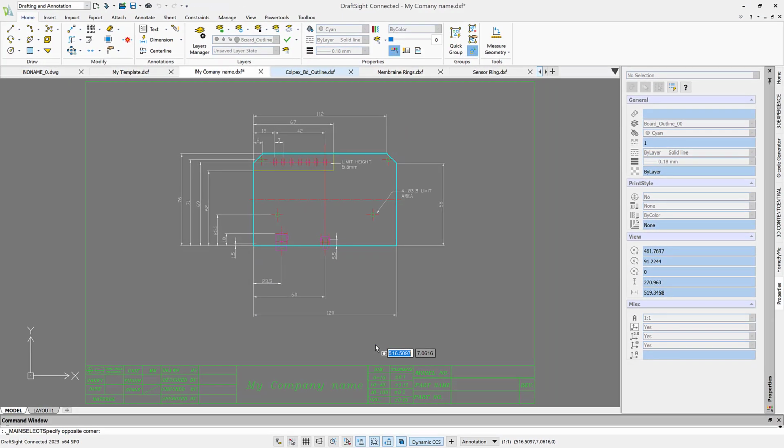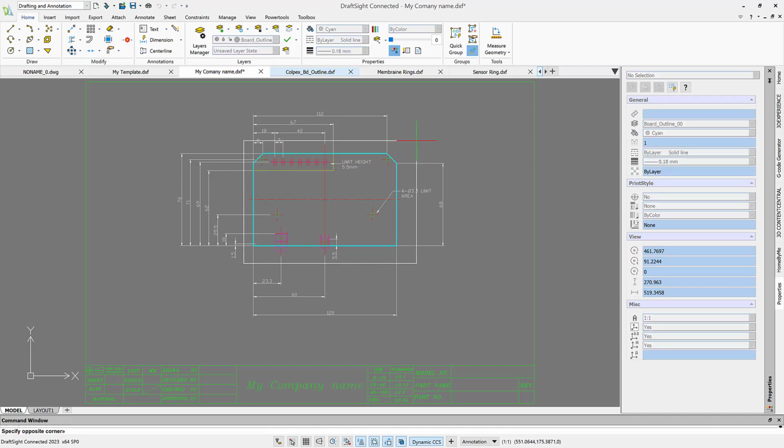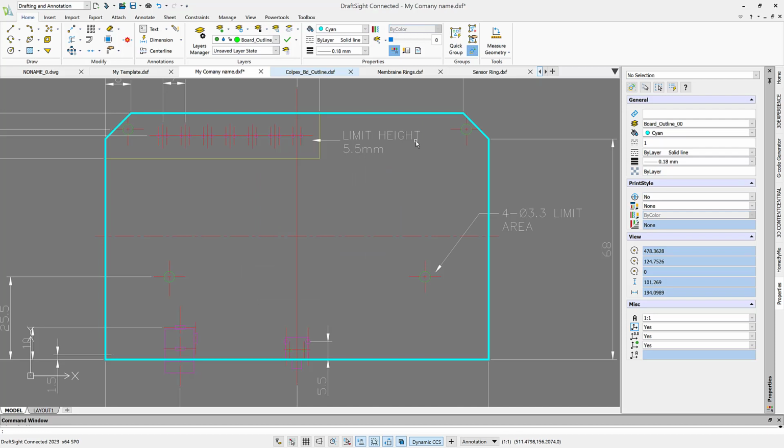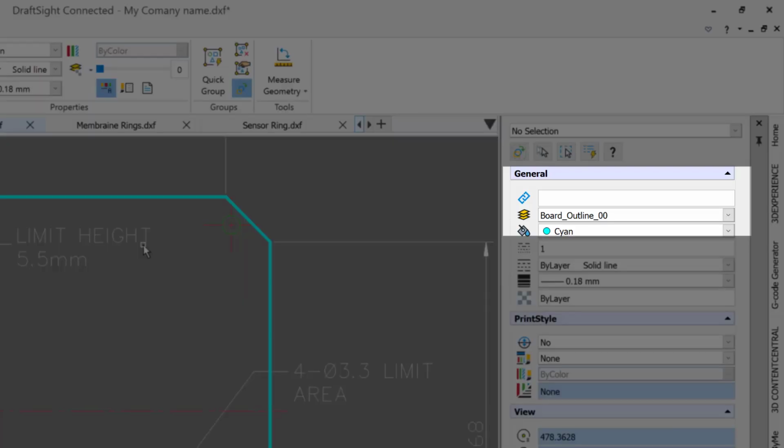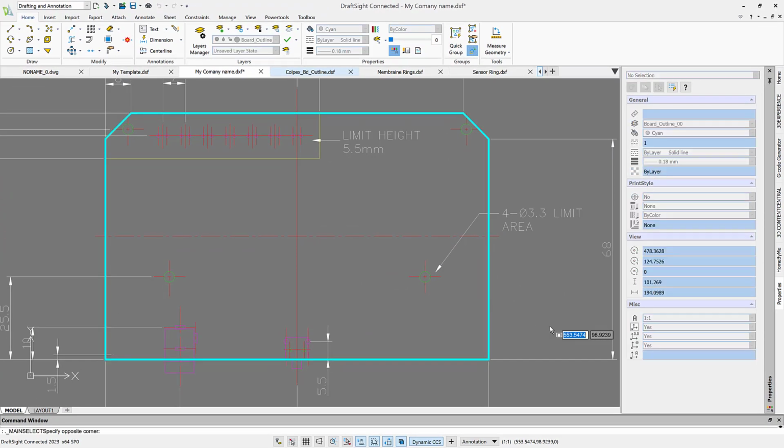And all you have to do is basically place mounting holes in the locations that they're shown here. Let me zoom in so it's easier to see. So you will place the mounting holes in these locations, basically using this board outline and whatever you brought in via DXF as your template. So you don't have to guess, and later, of course, you can measure it. And again, this board outline will become an intelligent board outline inside your PCB board layout software.